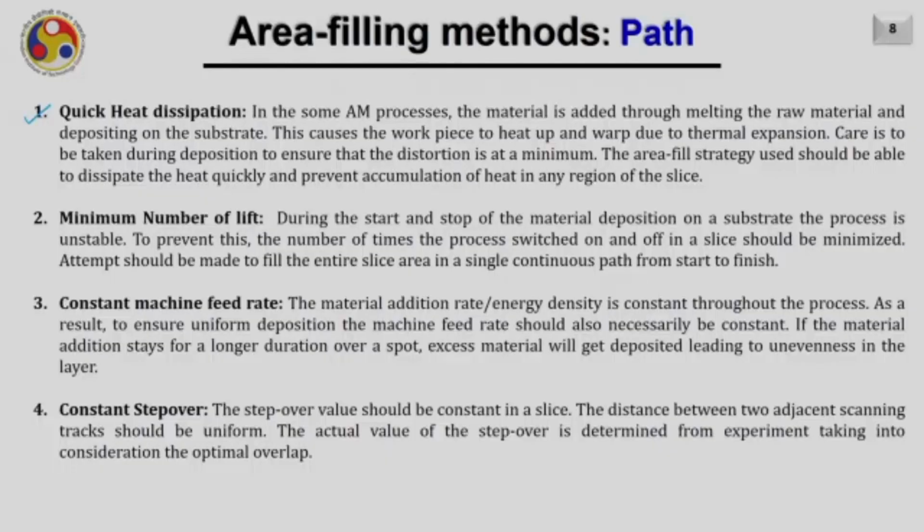Let us first discuss some of the important requirements or expectations from a scanning path or area filling path. Then we shall move ahead to the different types of area filling strategies based on toolpath. The first one is the toolpath should be such that it can quickly dissipate the heat from the slice.